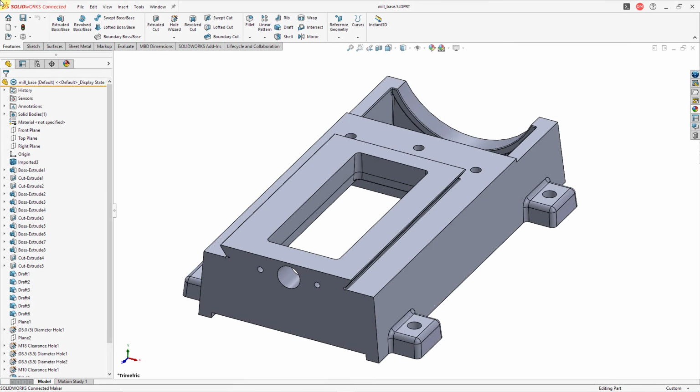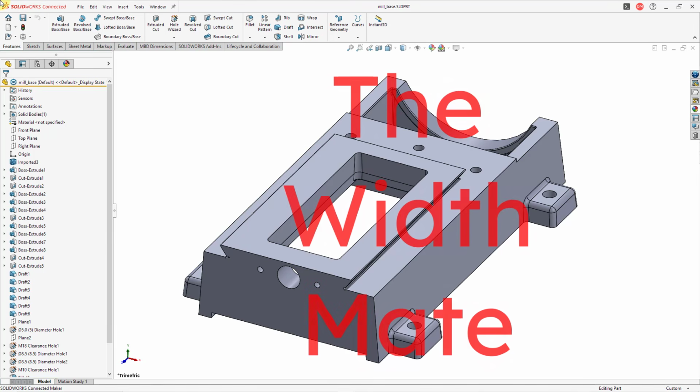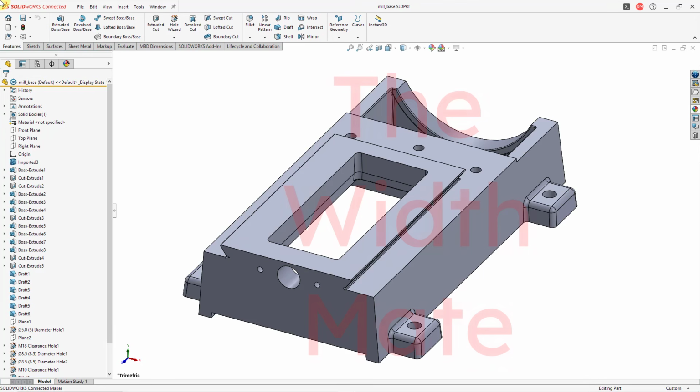In this episode of SolidWorks for Creo Parametric users, we will take a look at a mate that does not have a direct analog in Creo Parametric. Just as a reminder, a mate is the same thing as a constraint in an assembly in Creo Parametric. So in my SolidWorks session, I have three parts open that I want to make an assembly for.